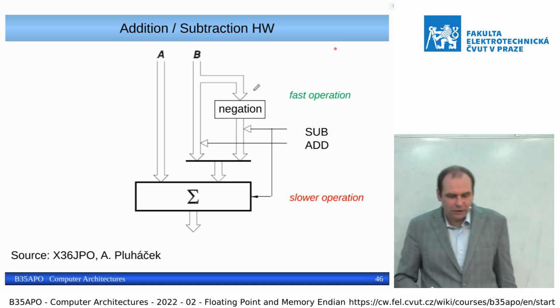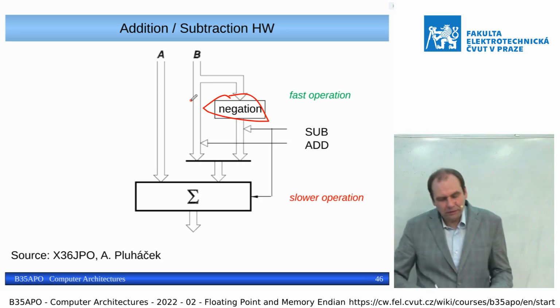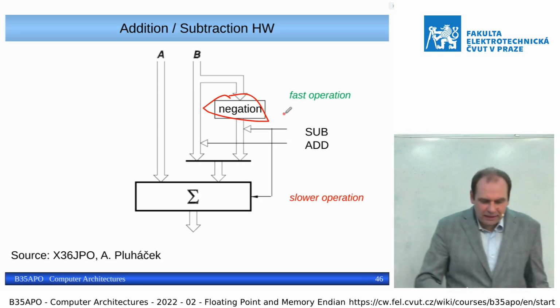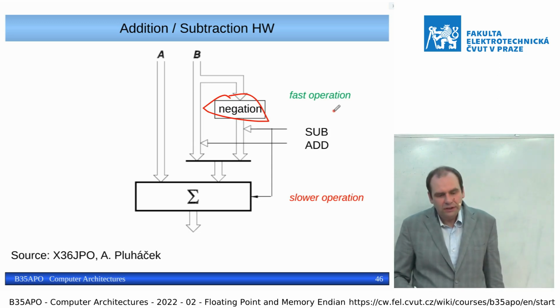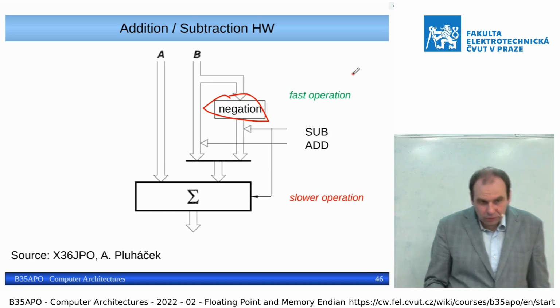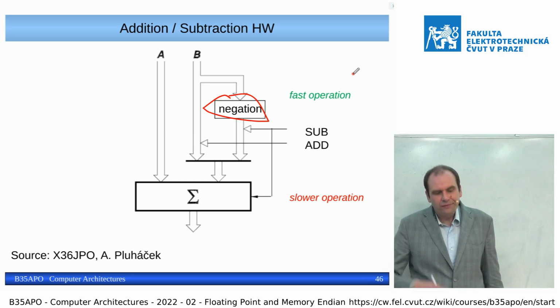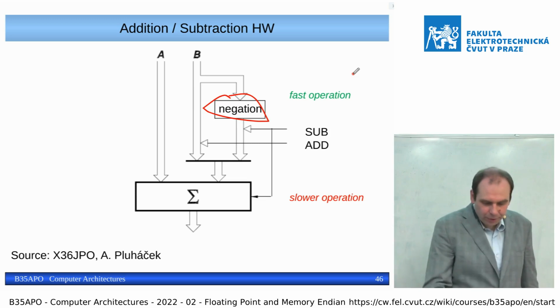In theory, we can build a subtraction as a negation and then addition of 1, because we have seen that for two's complement arithmetic, if we flip each bit to its opposite value and then add 1, we have a representation of the negative value with the same magnitude as the input number.